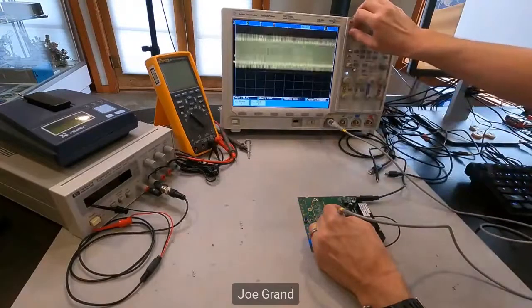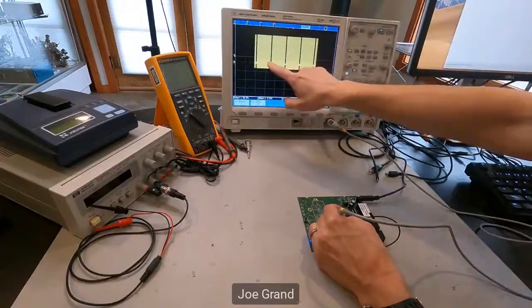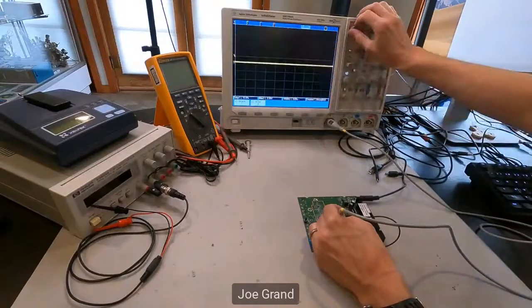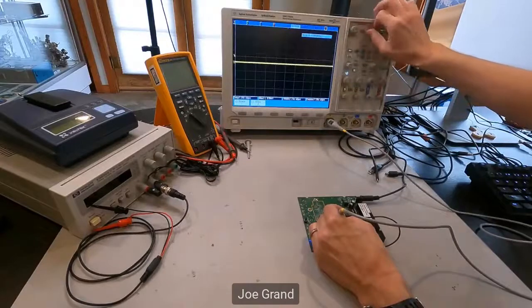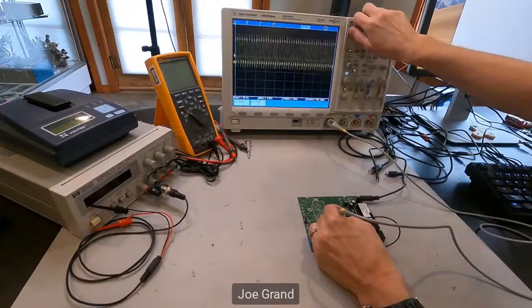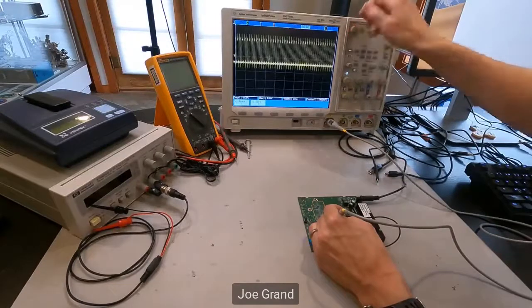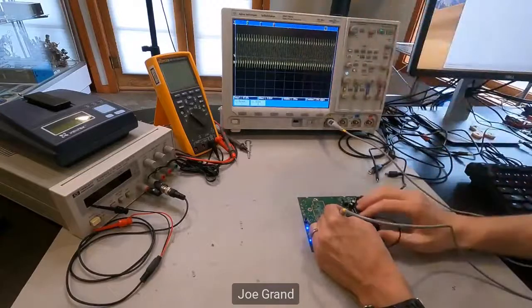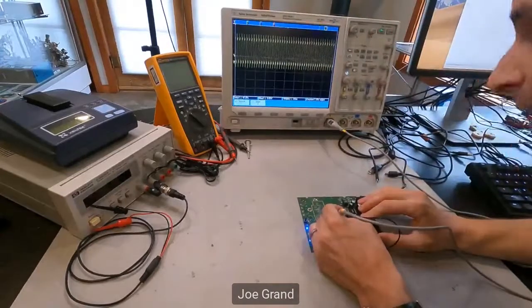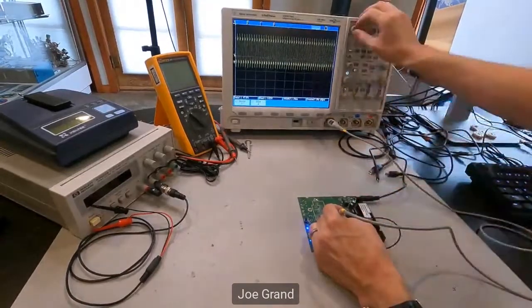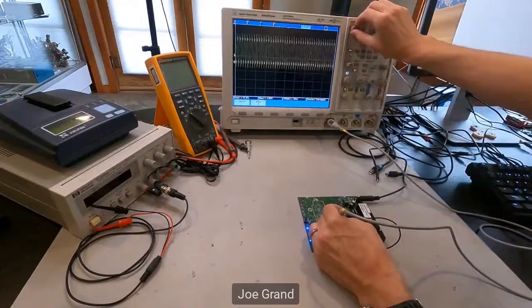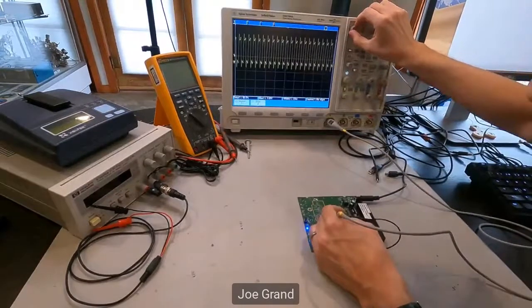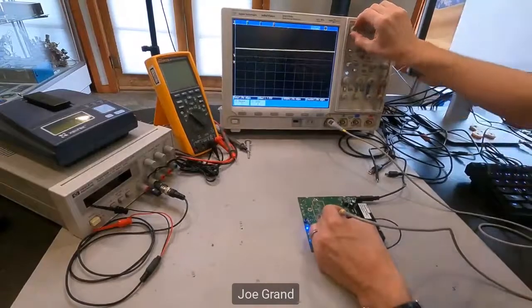So I don't know if you can see the oscilloscope screen, but we see a lot of information being sent across. That looks very clock-like. So that's probably the clock line, and then there's going to be an associated data line somewhere on the actual chip that is synchronized to that clock. So if we wanted to sniff the data off of the device on power up, we could probably do that.